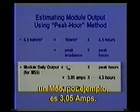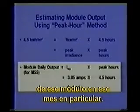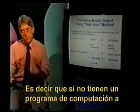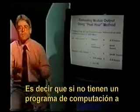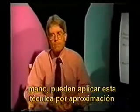For an M55, for example, that's 3.05 amps. And in this case, we would calculate 13.5 amp hours per day in that particular month from that module. It's another rough approximation technique given insolation data and if you don't have a computer program.